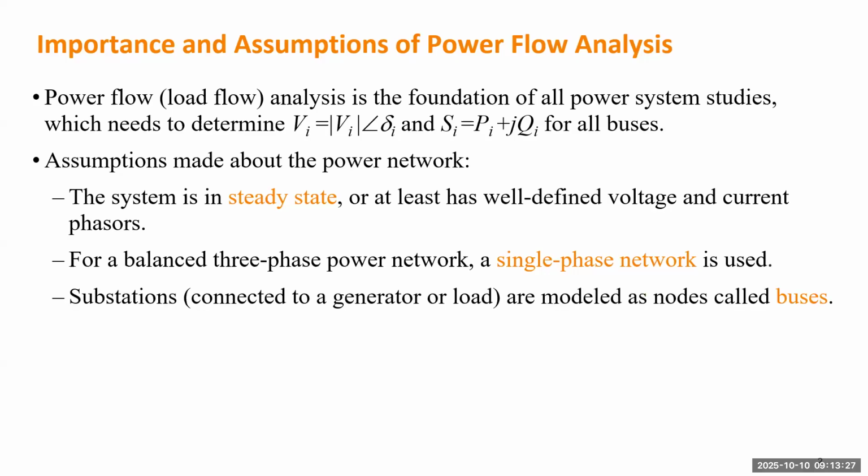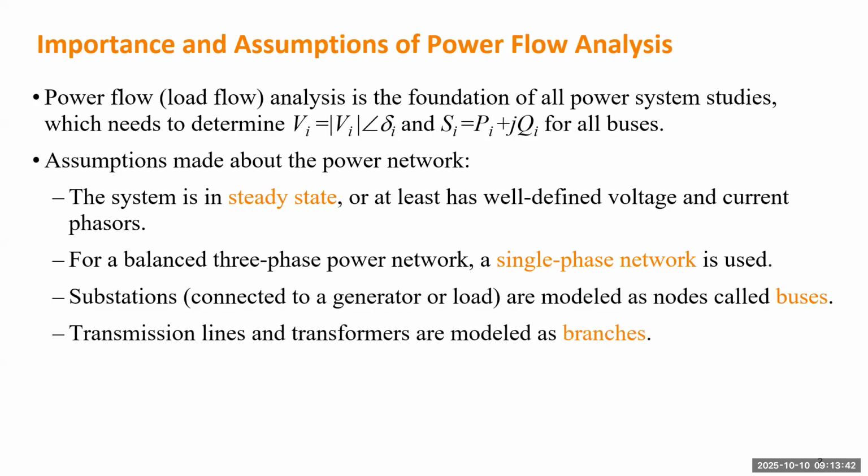And substations are called buses, which means even if they can have a very complex layout, each will be treated as a node or a bus connecting branches to other substations. Both transmission lines and transformers are treated as branches.